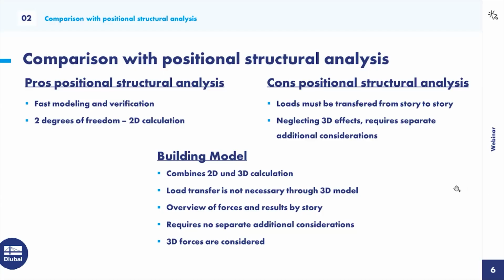The cons are when you design a slab or let's say a story, you calculate this, then you must make a load transfer from story to let's say to the walls, to the columns, and from there again to the slab. So you must all the time transfer new and new again until you are on the ground floor. And yeah, there you can make failure very easily when you forgot some loads.